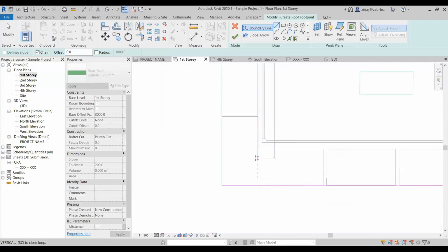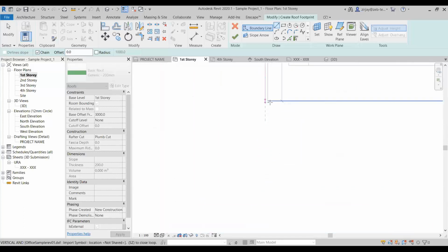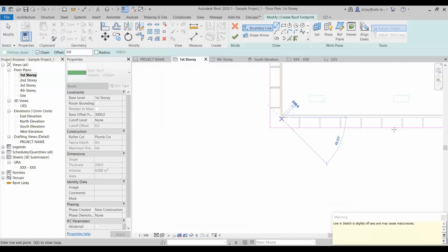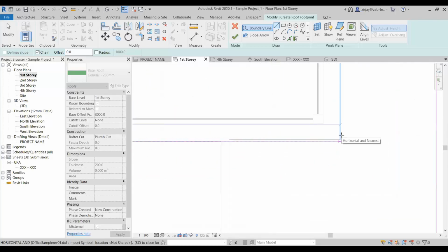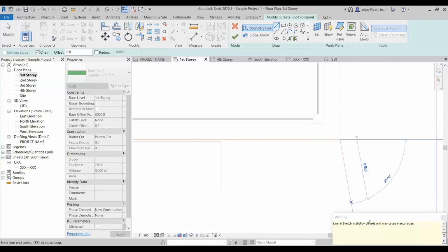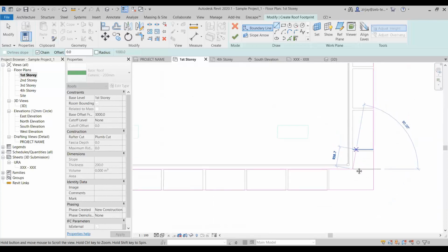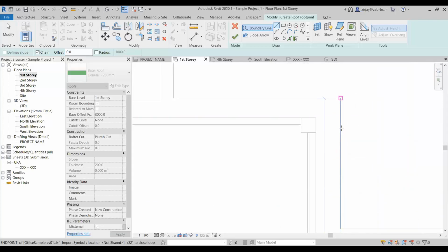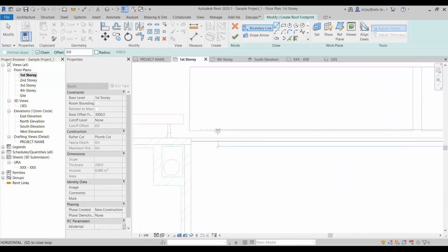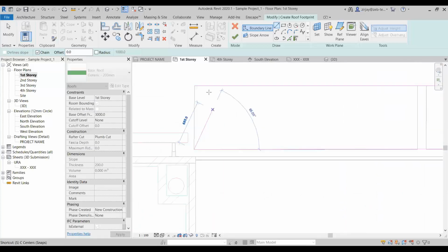As you can see, if I'm drawing straight, it's not really aligned. So it's the problem of the CAD file. It's just alerting you that, hey, your lines are not perfectly horizontal or vertical. That's why Revit is showing us all these warnings. But I don't care. I just want to trace the outline of this particular sunshade as it was drawn. And I'll just close it up.